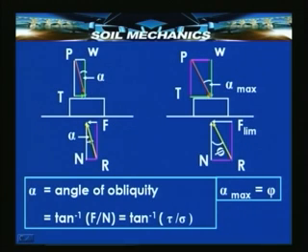The angle which R makes with the vertical will be the angle which P makes with the vertical, that is alpha. This is a situation when the block is in equilibrium, but let us increase the value of T until the block reaches the state of so called incipient slippage, that is T has now achieved its limiting value.